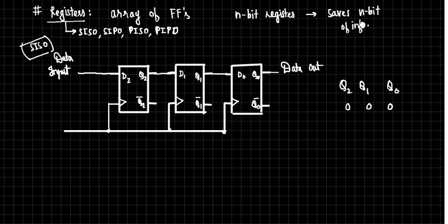That is how the active low inputs are defined. What I'm saying is, when preset is 0, output is definitely going to be preset. That means the activity happens only if you give a low signal. Such signals are called active low signals. I mean, the signal will actively do the job if you give low as an input signal. Let me draw that. So this is called preset, and that's how they are given.